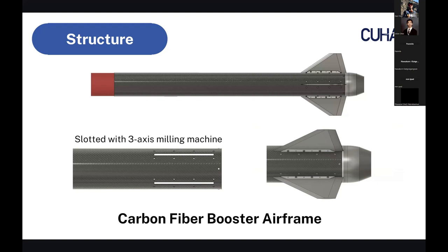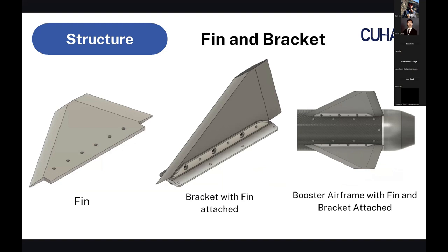And next are the fin and bracket designs. The fin dimensions and features: the leading edge would be 1.063 inches this time, and the length would be elongated to 9.84 inches. The height would be slightly taller at 4.134 inches, with an additional tab height of 0.551 inches.